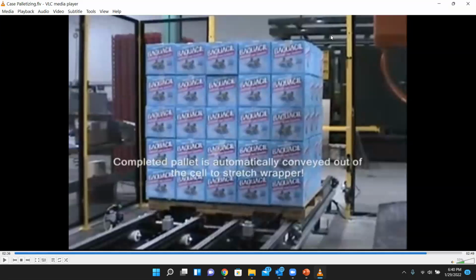It depends on the factory floor where you have the boxes coming in and where you have the pallets, where you have the sheets. Okay, so if you are the engineer who is tasked to design the factory, you have to take time and figure that out. What is the most efficient, most cost-effective design for this? If you design the factory floor where you have pallets, the sheets, and the conveyor belt on which the boxes are coming, in a pretty tight configuration, maybe you can have just one manipulator with a 3-in-1 end effector to do the job.